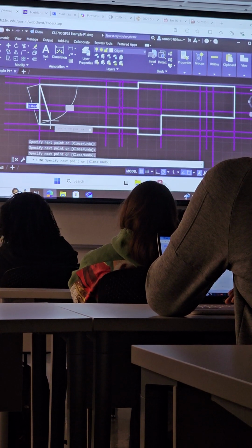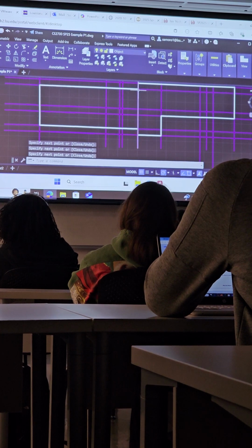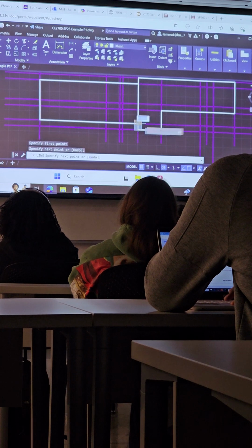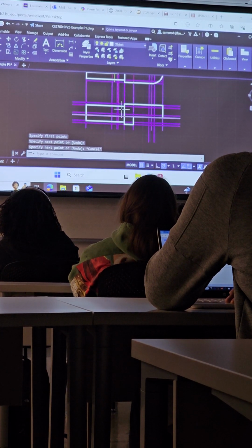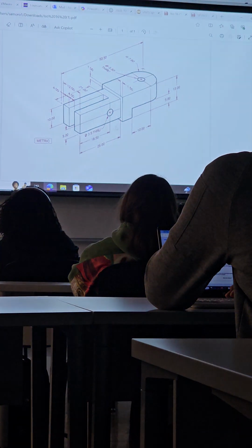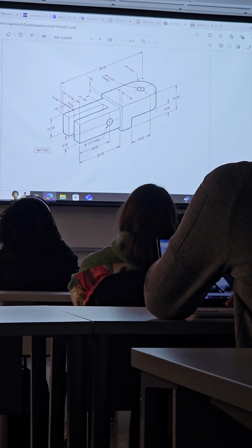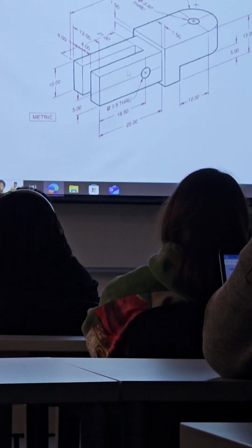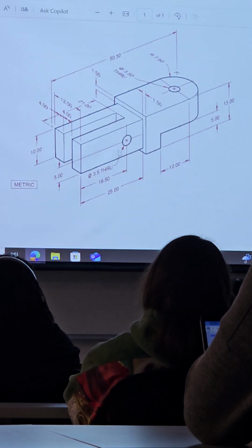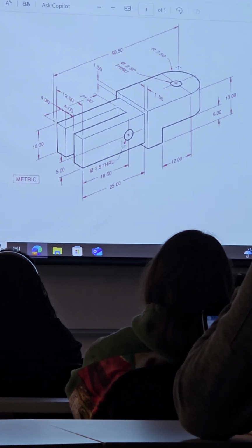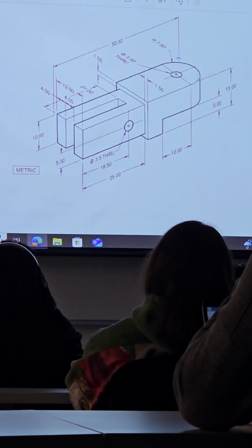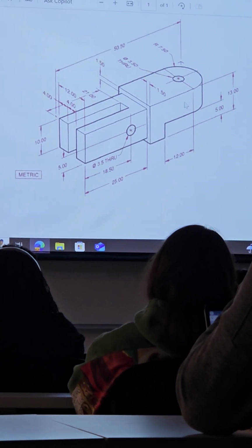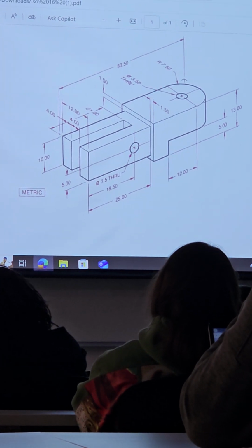Okay. I think I also need an object line in here. Okay, give me the thumbs up. Okay. So, what do I have so far? I've got an area that corresponds to this L-shaped bit, and I've got a rectangle that corresponds to this piece of the floor. What I don't have is an object line for this hole. That's going to be a visible edge. And then I also need some hidden lines to reflect the fact that this hole is penetrating through the thickness, this 8-unit thickness of this piece here.